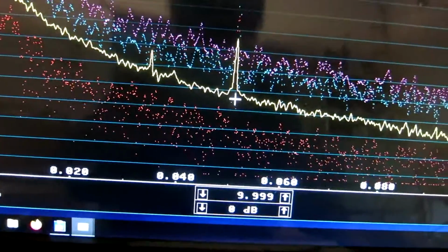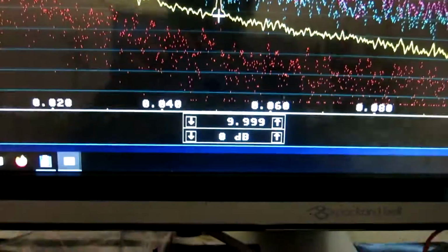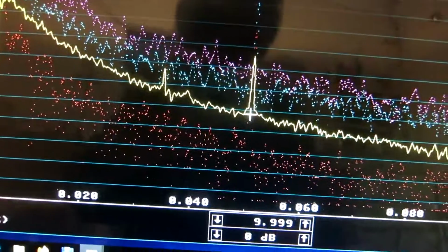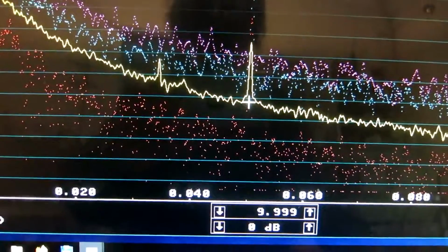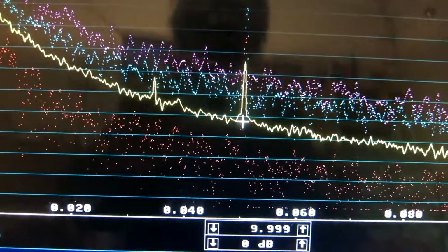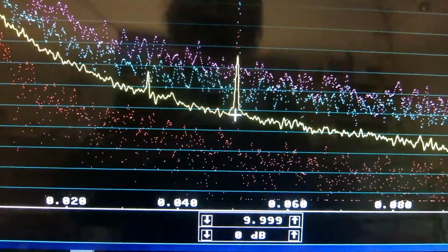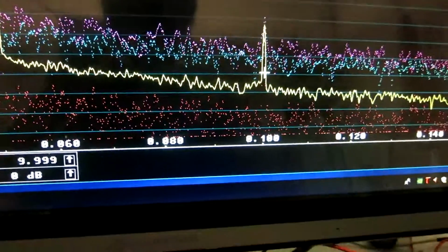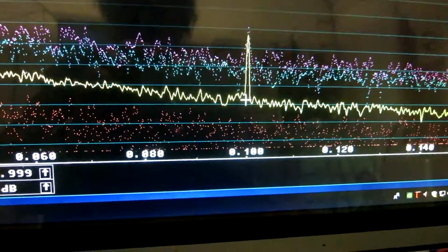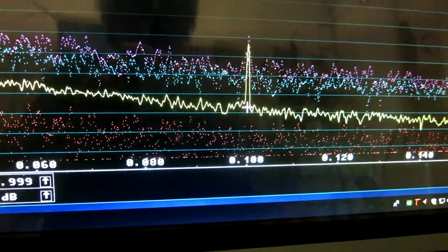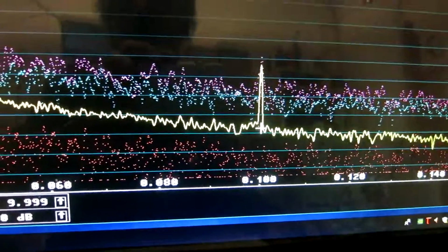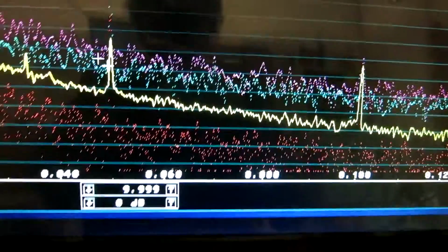I can evaluate phase noise here at 50 Hertz. I had before minus 156.1, and that looks perfectly in agreement with what I see here. And at 100 Hertz, the old value is minus 164, and that is where I have the mouse now. So it looks also like as before.